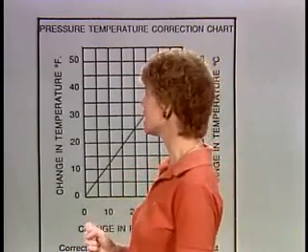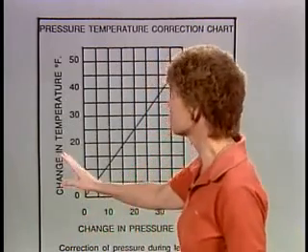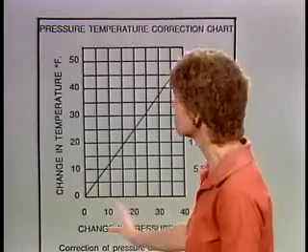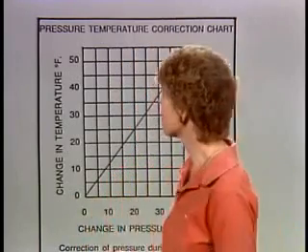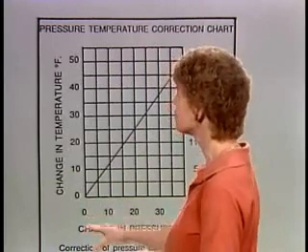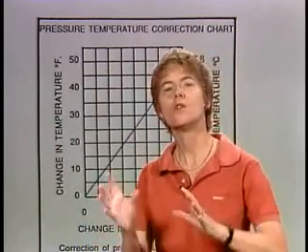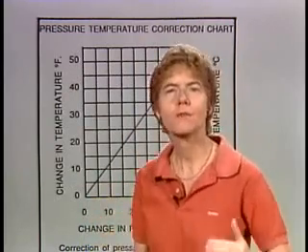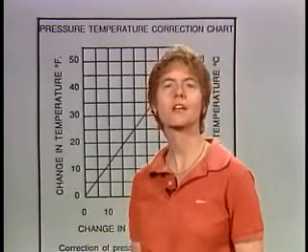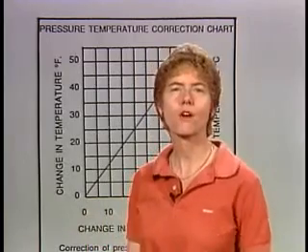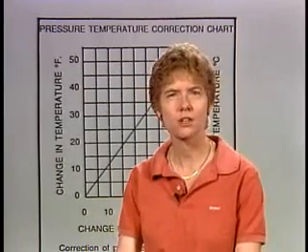What they're basically saying is that when the temperature changes, the pressure will also change even if you do not have a leak, and on top of whatever pressure change you're allowed due to the change in temperature, you are allowed a 5 psi difference as far as leak is concerned in a 6-hour period and still have it pass as far as a leakage check is concerned.